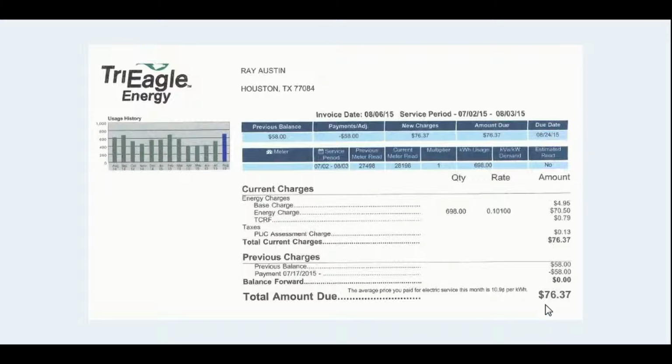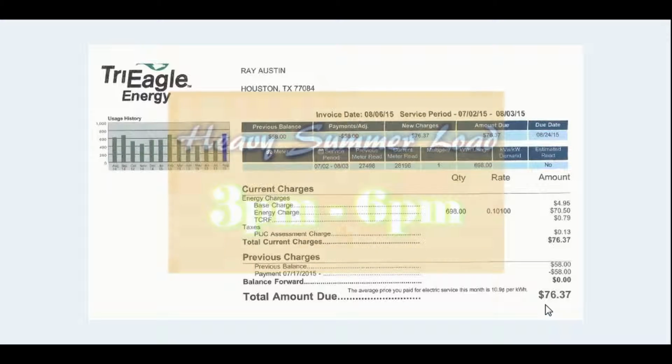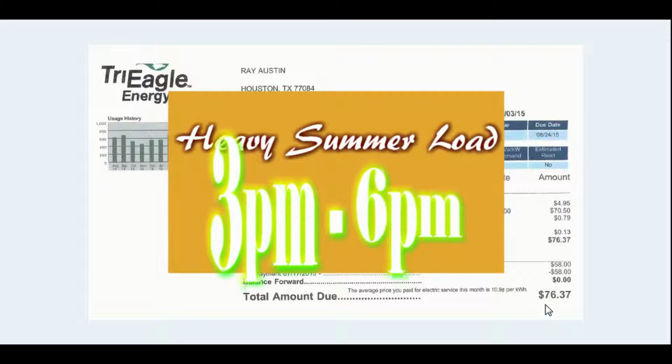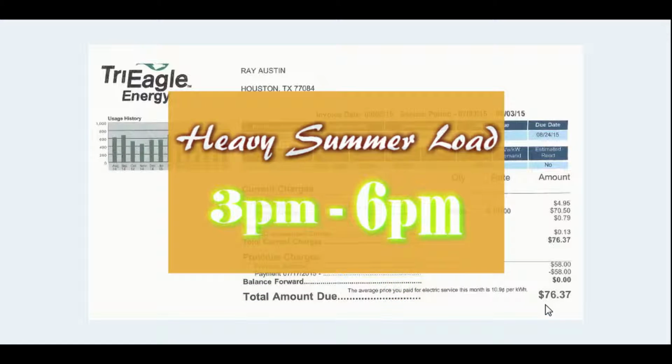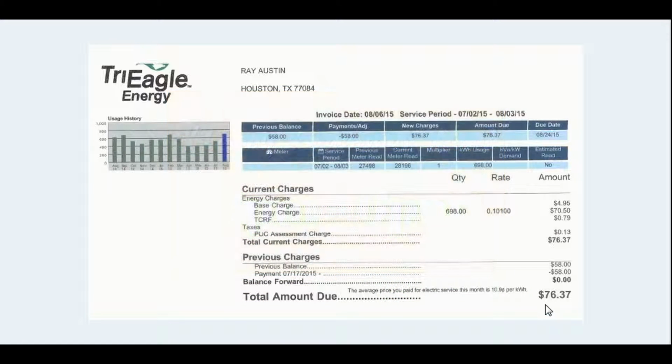Everything is going to either two-staged or multi-staged air conditioning, and the reason for that is that there's probably maybe 3 or 4 hours a day where the load on the house is severe. So if your air conditioner is either on or off, you're basically paying for a turbo mode on the air conditioner all the time. No matter if it's running, it's in turbo mode.